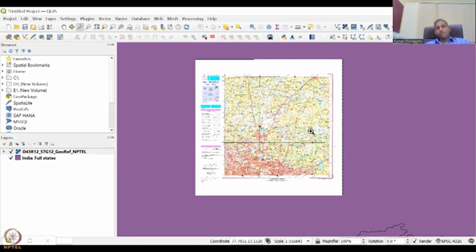Until then, please try multiple times. Do not switch your latitude and longitude, east and north. Be careful with the naming. Your east, X, which is given in the georeference tool, is longitude. X axis can run like this, it can also run like this. So X is your longitude, and Y is your latitude, and then you zoom into that line which intersects and find your exact center.